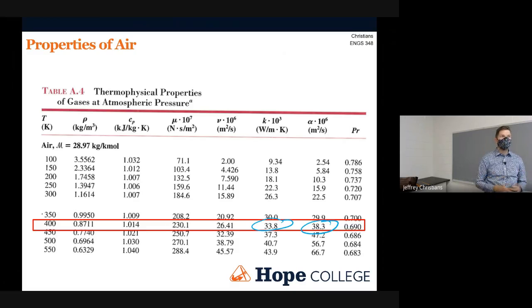And even changes that in some ways make your system worse, if they give you turbulence where you didn't have it before, will make your convection better. Because as you change the type of flow, whether it's laminar or turbulent, that changes things very significantly.